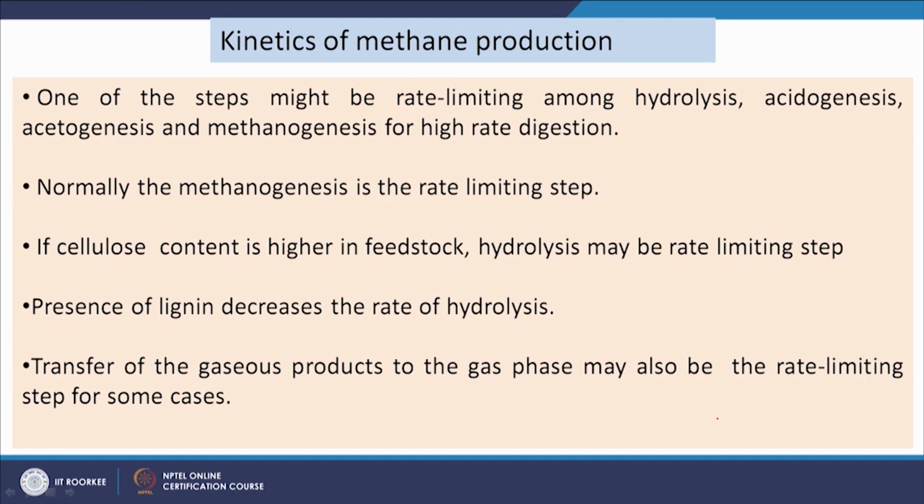But if cellulose content is very high in the feedstock, then the hydrolysis step may also take more time. If lignocellulosic biomass is present, even after pretreatment, that will have more cellulose, hemicellulose etc. So, the hydrolysis step may be longer. But in general, for simple types of compounds, the methanogenic step is the rate limiting step, and